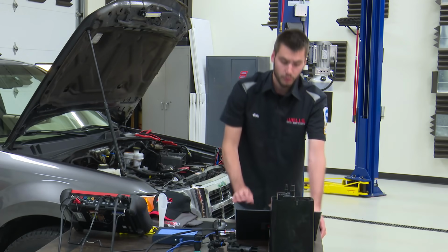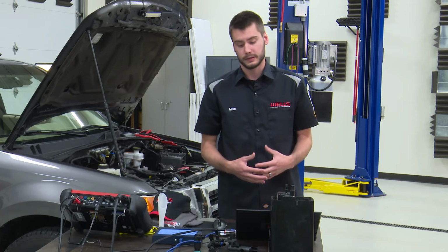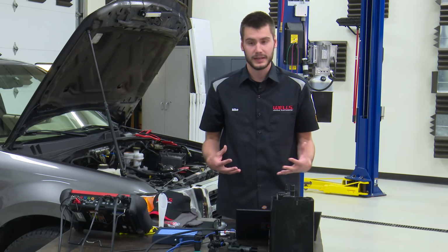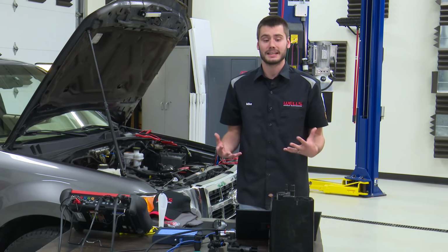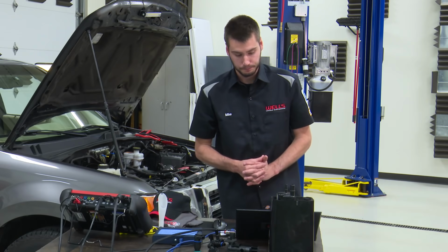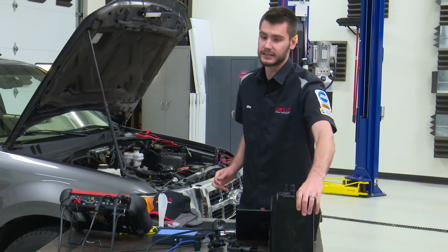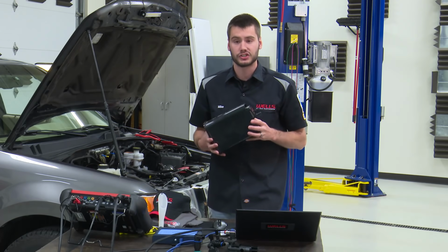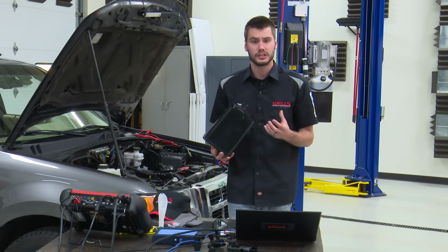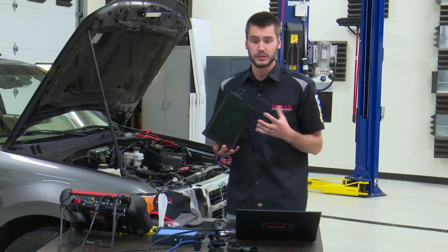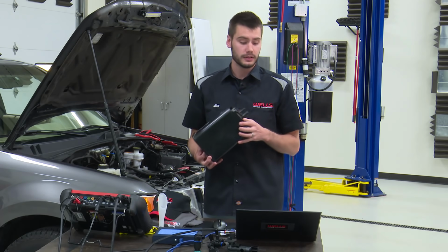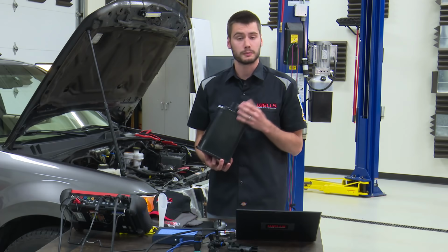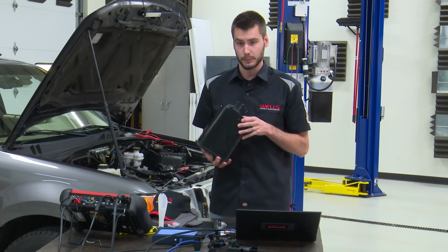All right, so we have a vent solenoid, going to be normally open. Our vent is basically exactly what it sounds like. It is a vent for the system, which is connected to our vapor canister. This guy here has activated charcoal inside. The goal of this is to store fuel vapors. The activated charcoal absorbs those vapors and holds onto them until the purge solenoid is open and the engine's ready to burn them off.